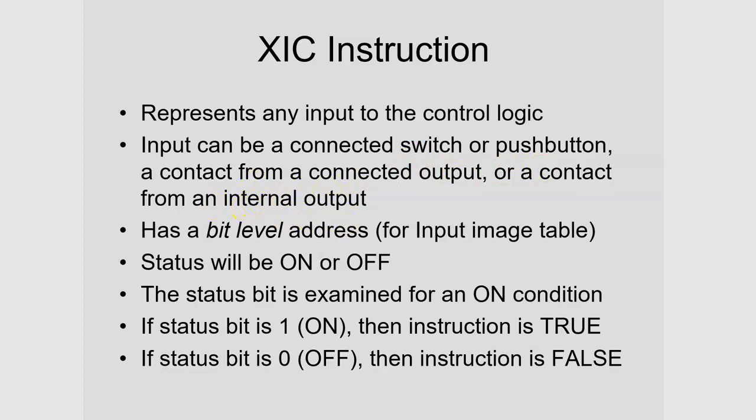We'll talk about that in a later PowerPoint. The examine if closed instruction is a bit level instruction. Now it says for the input image table. If you think of it as just a bunch of cells, 16 cells stuck together, in each cell you can hold a 0 or a 1.